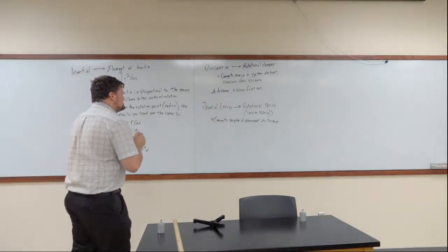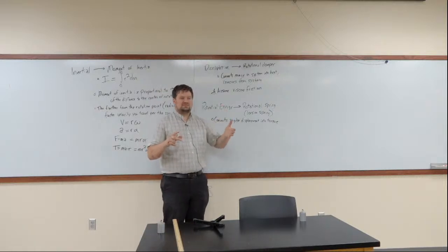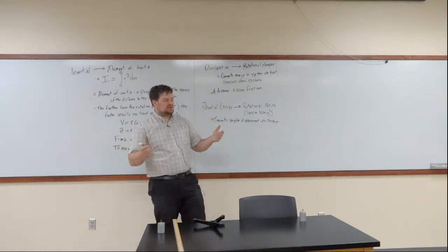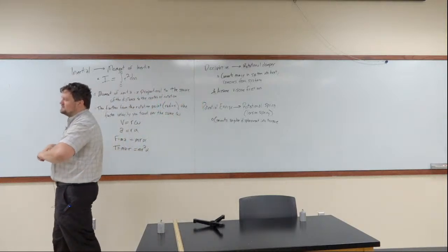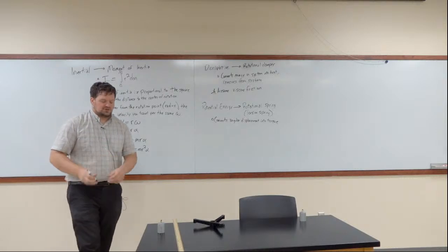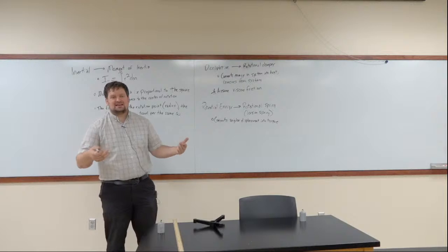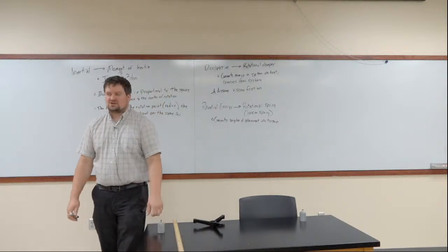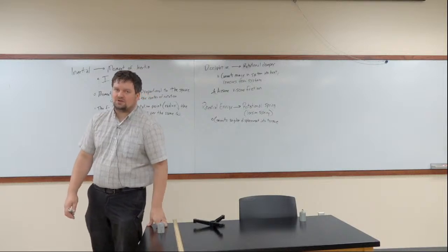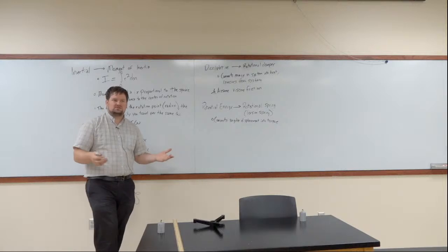All right, so potential energy, this converts angular displacement into torque. You rotate one end of the spring relative to the other end of the spring, it creates a torque in the spring. Now, there's one reason why this is very important. I've told you before, if I push on this table, it compresses the table. This table acts as a spring. Okay? What that means is a certain amount of load on this table will cause a certain amount of displacement, which is how a spring works.